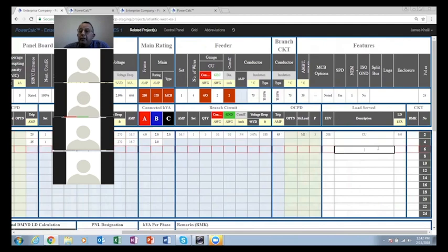All right, now again, as it happens, and everybody knows that, mechanical is probably at the last minute going to go ahead and change their mind about the mechanical equipment. So let's say now, I don't know, 5 o'clock is the deadline today to issue the drawings. The mechanical comes to you at 11 o'clock in the morning and says, oh, by the way, I changed my mechanical equipment in here. Now, in the old way, I have to go ahead and recalculate everything from the circuit all the way upstream until I reach the MDP. But here I can just go again to the wizard and change that value to a 12.